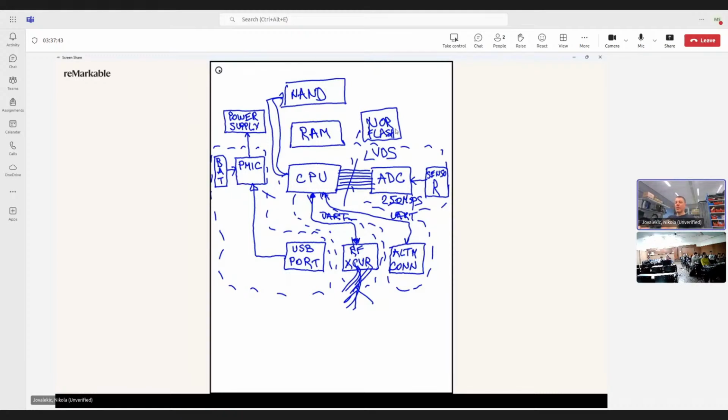Okay, so more or less, we are there. There are some small things we need here. Program the CPU, yes, a debug board. Do you want maybe some debug UART, so that when you start debugging your application you have an easier life? Yes, you will have some debug UART, for example, just for write-outs. Maybe you will have some LEDs. That's also good to have. Some dirty small things which ease the debugging sometimes.